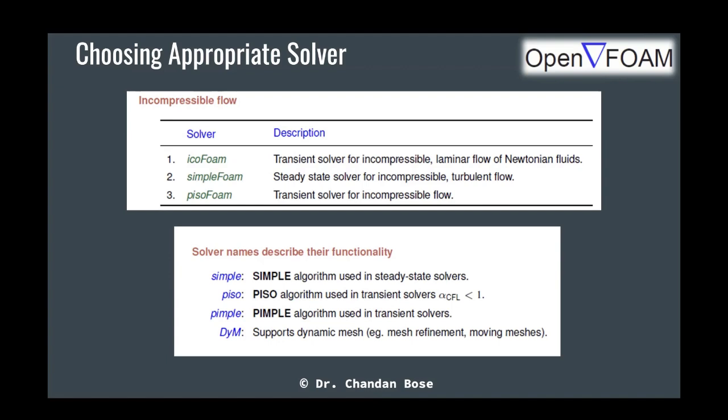Sometimes you can still have more than 1 as the CFL number but get a converged solution, because your calculation must be implicit in that case. And again, it relates back to the FD schemes, or the discretization schemes, and their orders of accuracy that you are using.